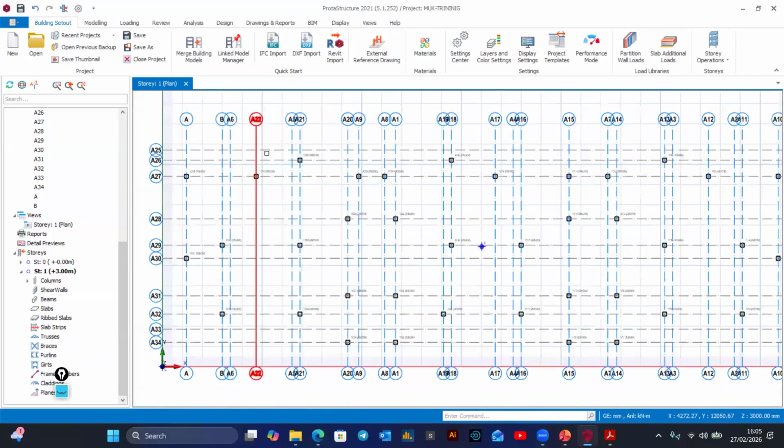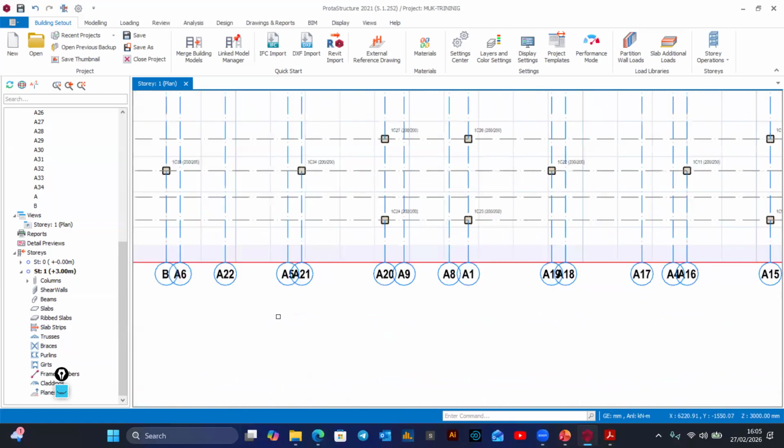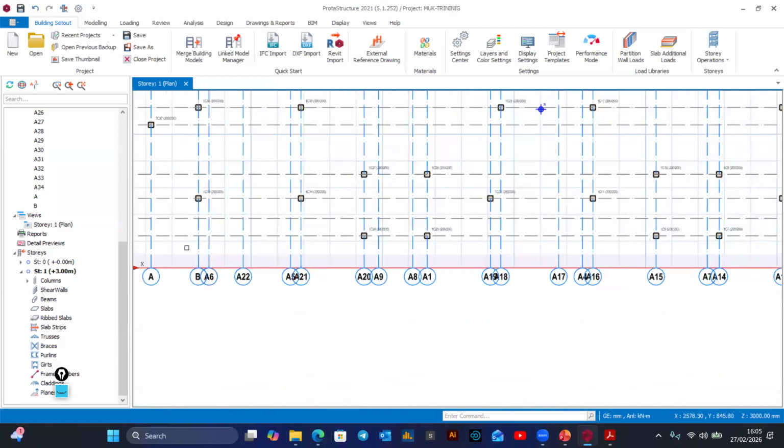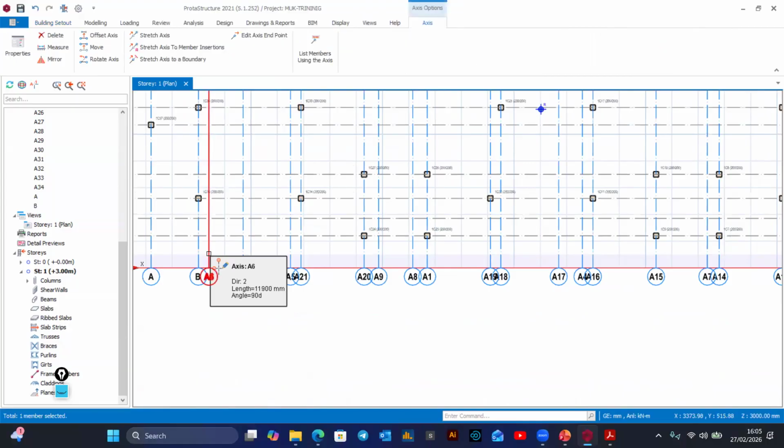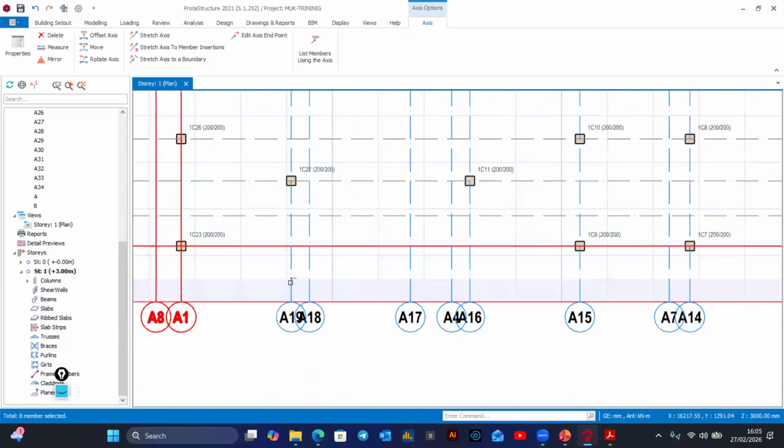So you select them in their order without skipping any. For example, we have stopped at B, click on the next one next to B, it's supposed to be C. Select it, hold Control, click on the next until they are all complete. As you hold Control, go on clicking on each in their order.